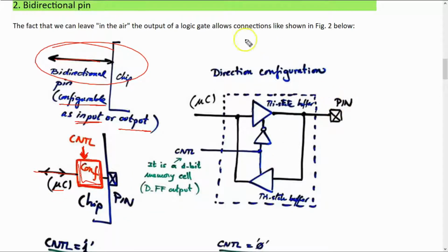So, and this is a kind of circuit to do that. You can connect like this, you see? The input, the output, and then the three-state gate that is driven by an inverter, and the same control is now driving the other gate that is connected like this in the opposite direction. So both gates have the same control signal, but you know it is affecting them differently.